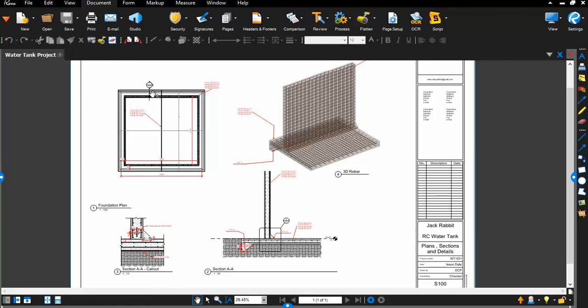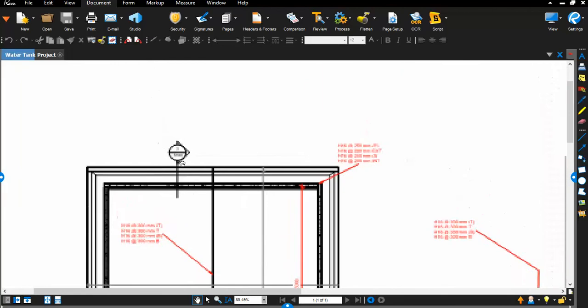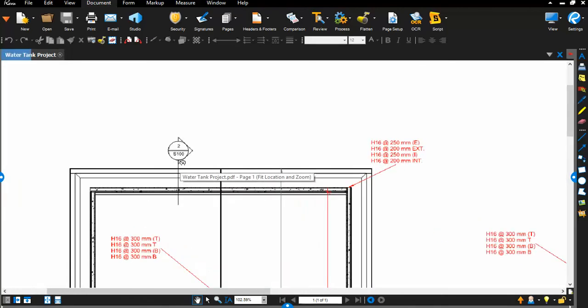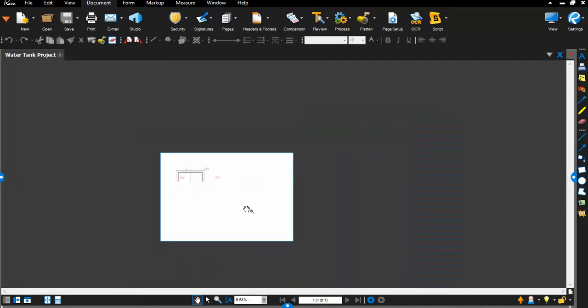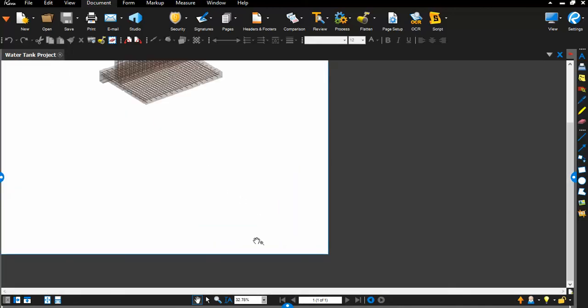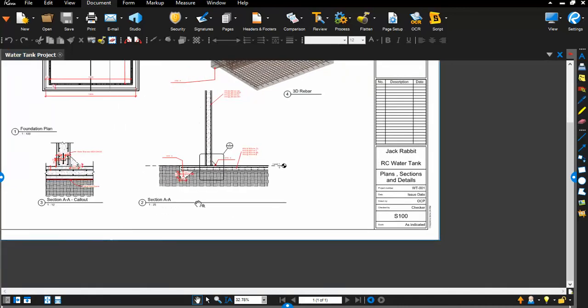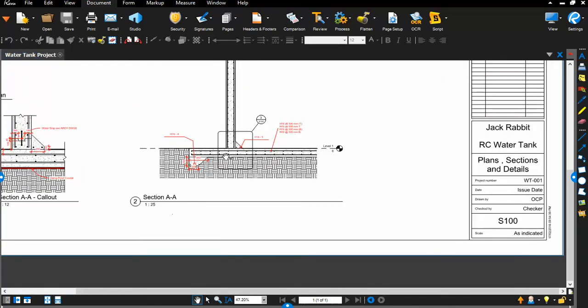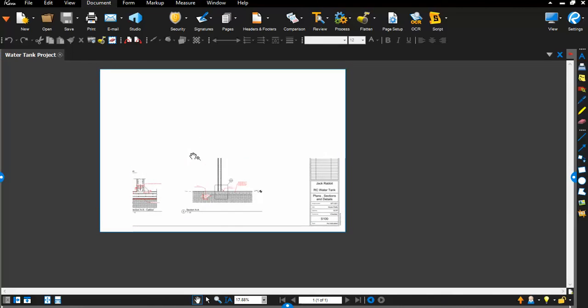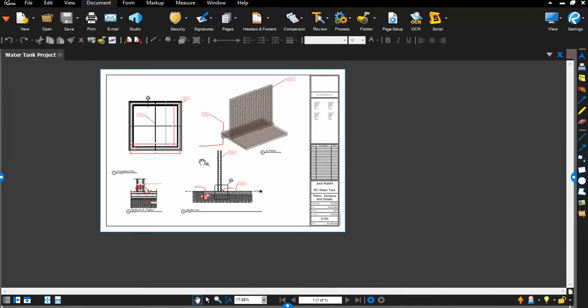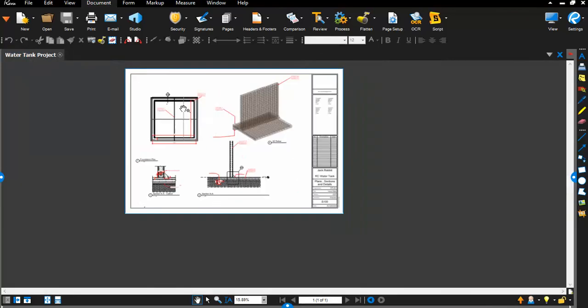be fine. Another thing, if you notice, it says here 2S100, which means detail 2 and sheet S100. Now, it's only one sheet. So this is sheet S100, and detail 2 will be this, section AE. So the person reading this will know where to go and where to look for certain details. Now, if you have many pages, this tag comes in very handy.